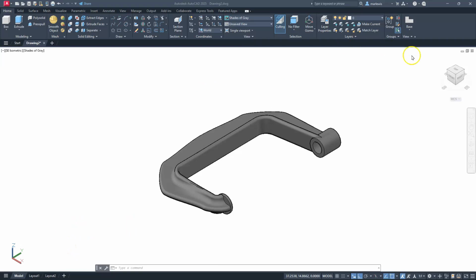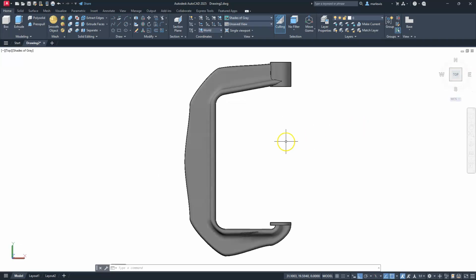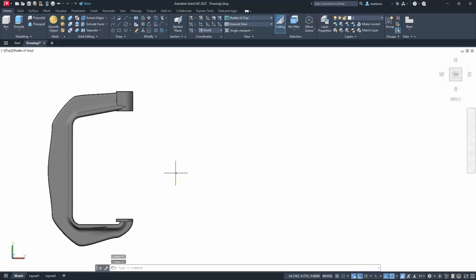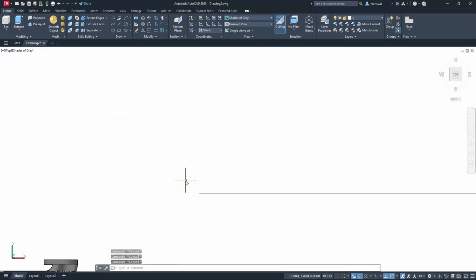All right. Let's look at this from the top view. Slide this to the side. I'll start working on my connecting rod here. So I'll start off by creating a line that has a distance of 8.875. Let's draw a line from here going up. And the overall radius of this part is going to be 5/8, which is 0.625, but I'll just use the